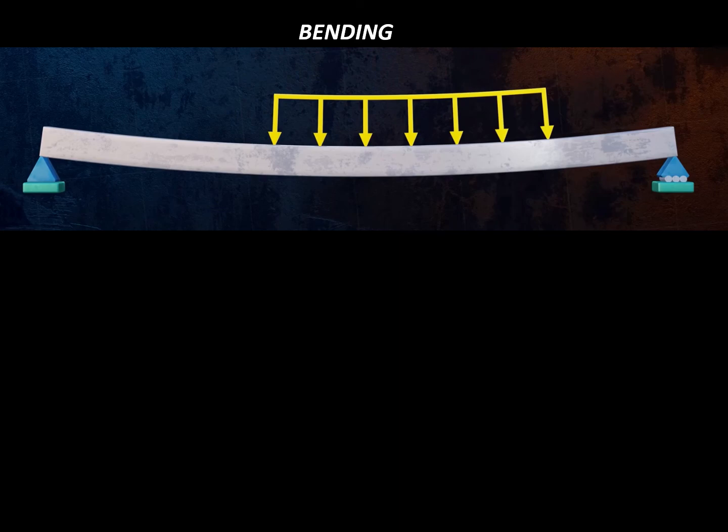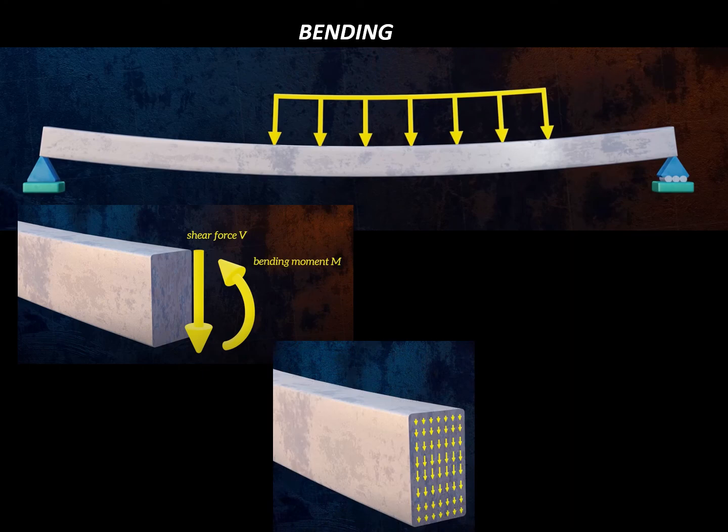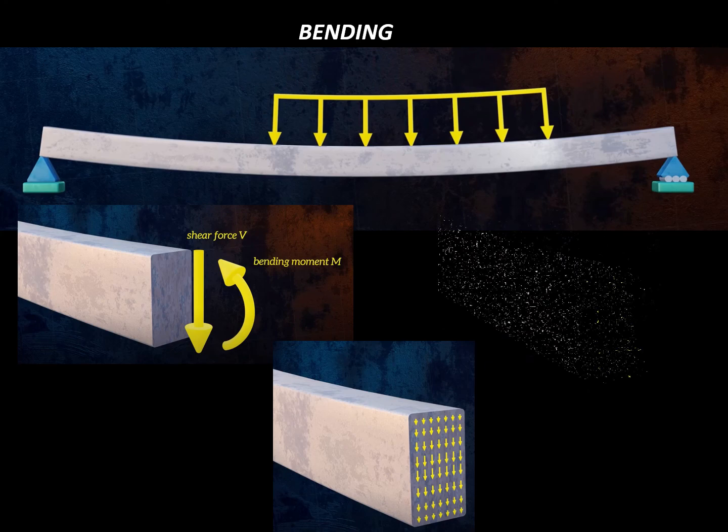In addition, if you look at the cross-sectional area of this beam, so if you were to think about lots of little disks, lots of cross-sections of this disk, they're trying to slide relative to each other. So there's a shear force also exerted. So there's a bending moment. The beam is sagging and it's bending into a U shape, but there's also shearing going on. So the shear stress is downward, that shear force, and the bending moment is, as I mentioned, complicated.